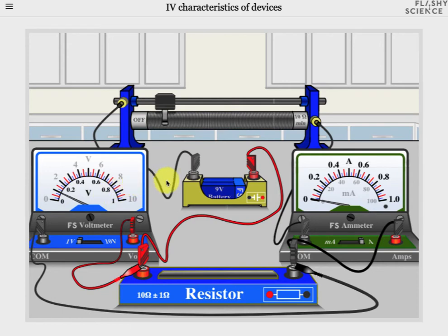However, it's difficult to measure the electrical current at the moment because it's so low. To overcome this problem, click on the switch on the ammeter to change the sensitivity and move to the scale shown in milliamps. This makes the measurement much easier, and we can now find the current passing through the device. We can now move the rheostat contact to several positions, and at each, measure the potential difference and electrical current flowing through the device.